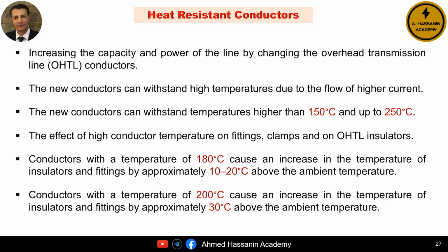As everyone knows, there is a continuous increase in electrical power consumption, and the common or logical solution to meet this growing demand for electric energy is to construct new transmission lines. However, there are two main problems with this approach. The first problem is the high economic cost of constructing new transmission lines. The second problem is the difficulty of finding new right-of-way routes or suitable paths for these new overhead lines. Therefore, engineers started to think about increasing the power transfer capacity and enhancing the transmission line capability by replacing the existing conductors with conductors having larger cross-sectional areas.